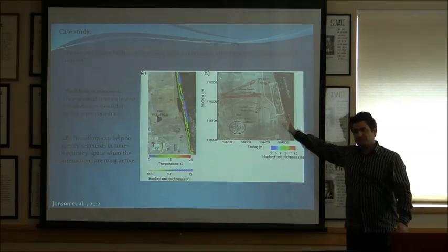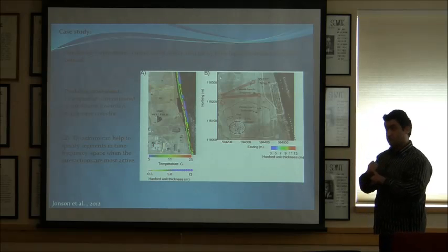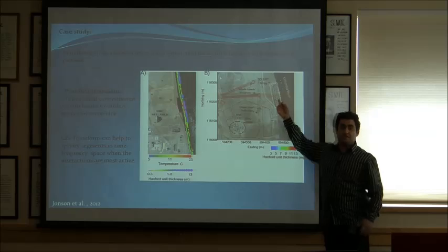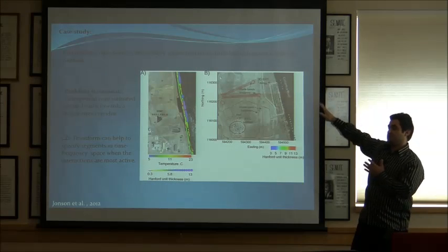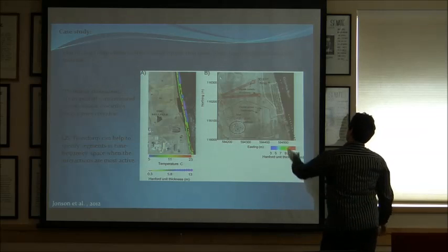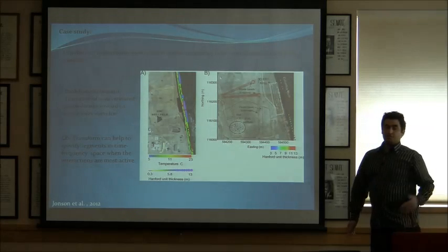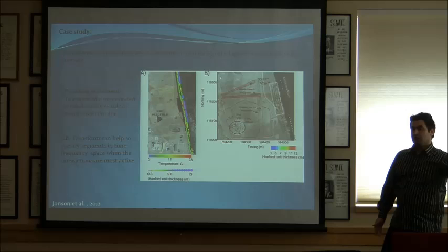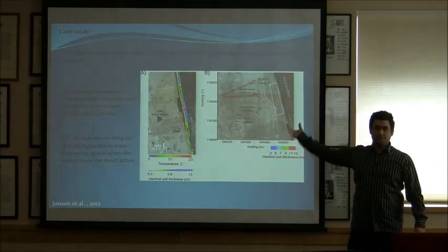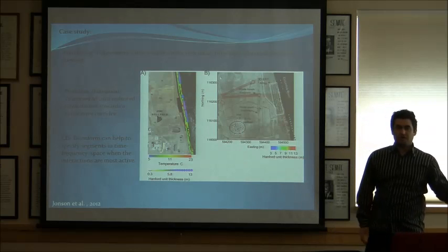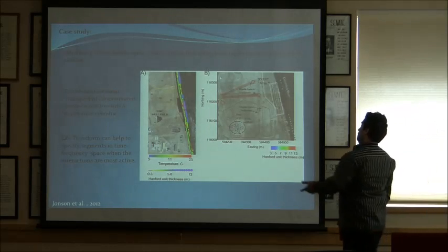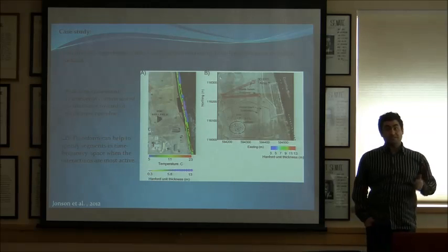So two reasons for this study: first, to verify there is a valley channel. Second, to find an alternative, faster way to invert or interpret the resistivity data, because traditional ways were based on just comparing different time-lapse images. With this method, the model, if I remember, had more than 100,000 mesh cells, but you can process the whole data within half an hour.